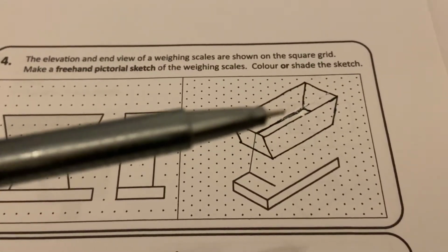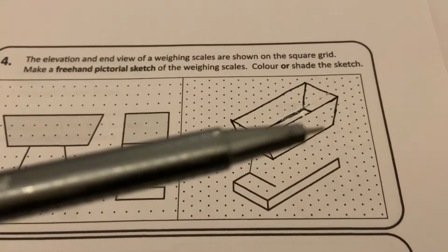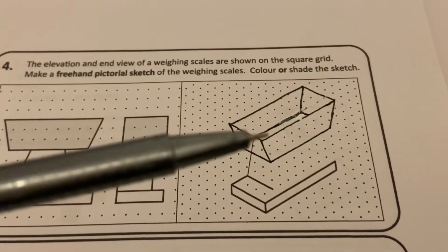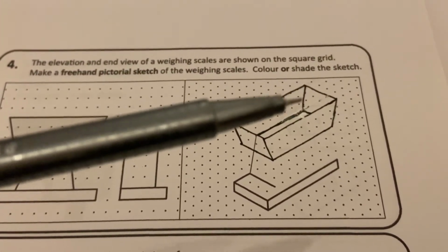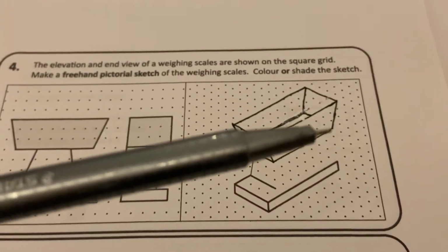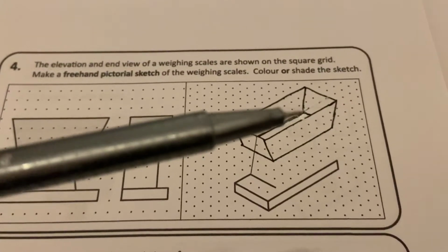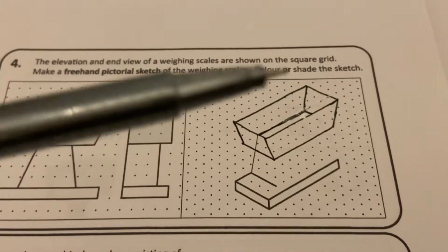So from that corner over 10, from this corner over 8, connect those together. Then drop down 3, draw this line going back. This line here is parallel to this line, and then that corner would be coming along those dots, and then it would emerge out here to give you the internal corner there.